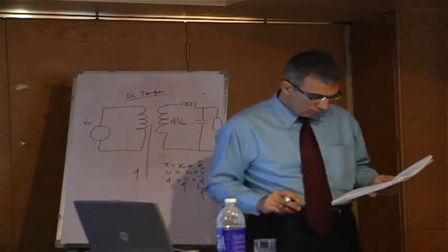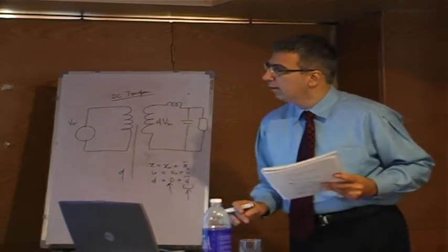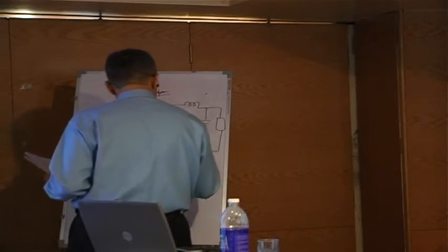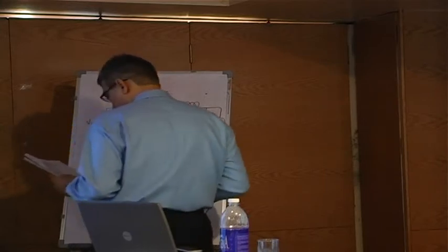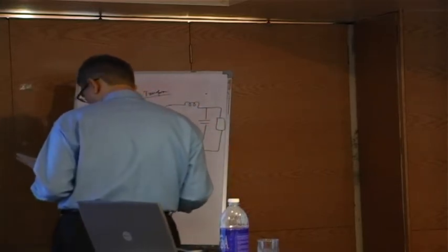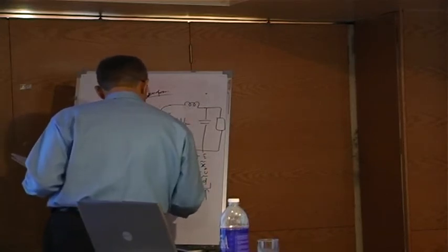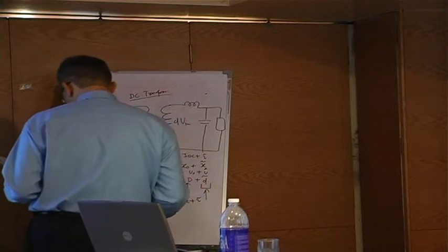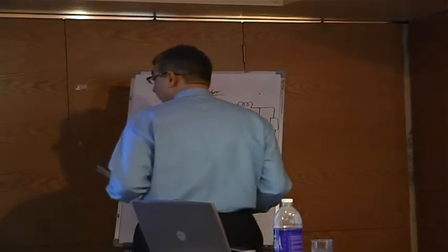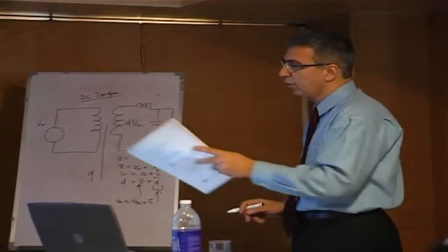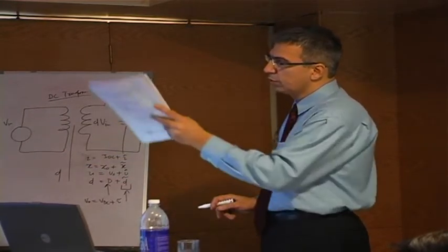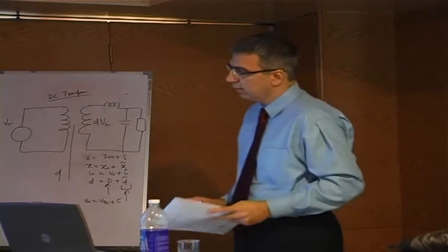Now, if you look at here, x is I, so we can say I is equal to IDC plus small perturbation, and your u is V output, which is VDC plus small perturbation. And then D is your duty cycle, D plus d perturbation. So that's what we have done in our state variable equation, and then you can essentially see how they play out when you substitute I with IDC plus I tilde.